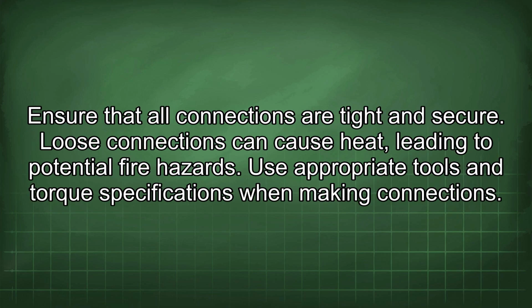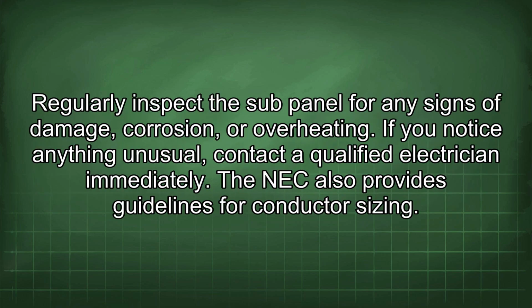Ensure that all connections are tight and secure. Loose connections can cause heat, leading to potential fire hazards. Use appropriate tools and torque specifications when making connections. Regularly inspect the sub-panel for any signs of damage, corrosion, or overheating. If you notice anything unusual, contact a qualified electrician immediately.